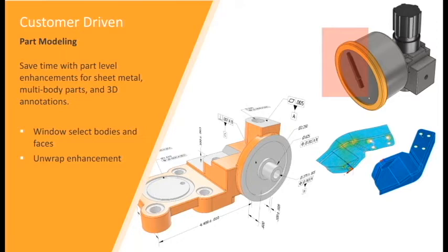So if you are essentially using a .ipt file to create maybe some pre-production type of designs, instead of actually creating an assembly, just use your .ipt file and create separate multi-body parts, and you can now window around certain bodies, and those bodies will highlight, and you can quickly maybe either turn off those multi-body parts or change the color of a specific multi-body part.